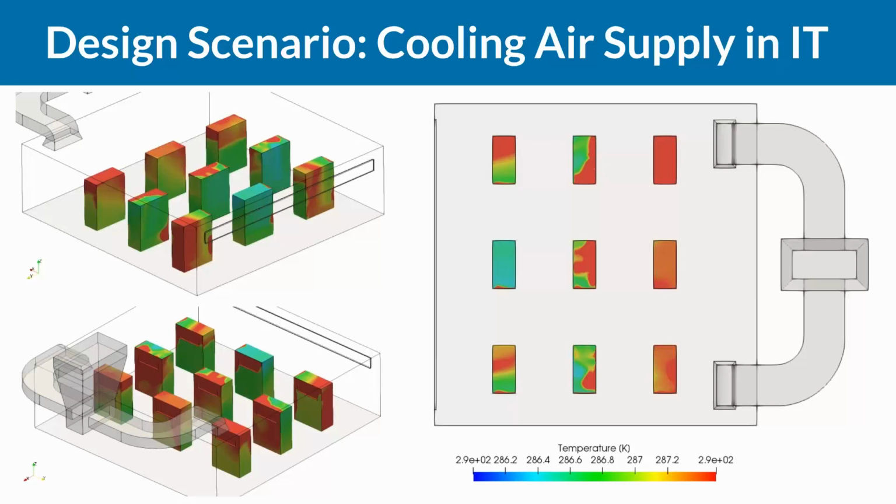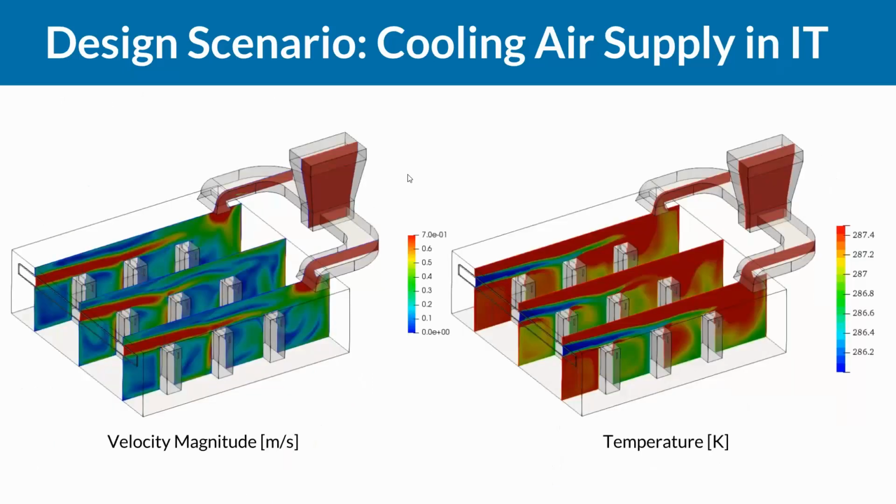And now the designer and also the engineer sit together and start thinking about finding the best option, or finding the optimum design that will help you get a smooth, or let's say homogeneous, distribution all over these heat sources, or in this case our clusters or computers. To do this, we use different post-processing techniques, starting with slices.